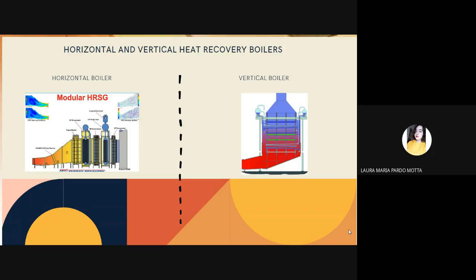It needs a support structure, being overall a more compact and cheaper boiler, since it requires little metallic support structure when the elements are hung from the ceiling. The insulation is usually internal to avoid using alloy materials and special joints in the housing. The insulation material should be covered by a sheet to protect it from the impact of water or steam in the event of a tube break.